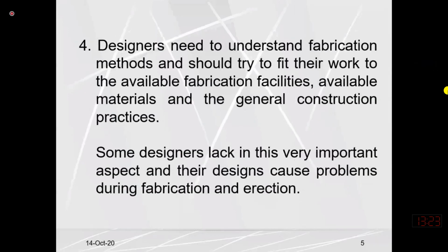Designers need to understand fabrication methods and should try to fit their work to the available fabrication facilities. Fabrication means that I must know whether in my crew I have a skilled person who can weld, or a skilled person who can install the rivets. If I do not have a skilled person who can install or fabricate rivets, then I will simply use a bolted connection. So we must know how the members are being fabricated.